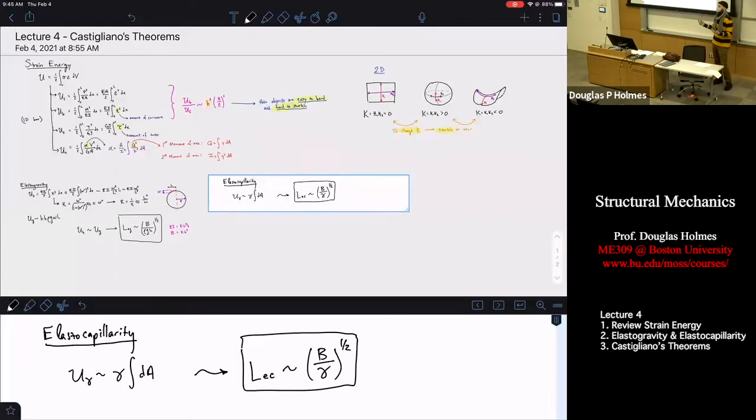But this is also used a lot by people making microfluidic devices in soft robotics, in lab on a chip diagnostics, where you want to move small amounts of fluid in places. Well, to do that, you have to make really small channels, and you have to put fluid in there. If that channel is small, it's usually thin as well. Usually you have a thin membrane over this thing. There's a length to that channel in which, if you're below that length, the fluid will pull the top of the channel down, and it'll just plug the channel. Here's your channel, between two sheets of paper, but just imagine this thing really small. That length will tell you whether or not your fluid is going to cause this sheet to be bent down, which is not going to let any fluid flow through your channel.